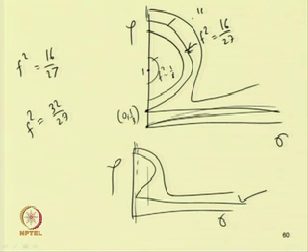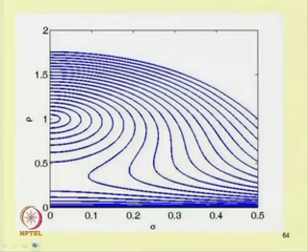When we have a single branch, that is stable. When we have three branches, the upper and lower are stable and the middle one is unstable. Similarly, the right hand side branch also is unstable. The actual stability of this curve can be studied by perturbing this equation, and one can find whether the system is stable or unstable by plotting the response of the system.